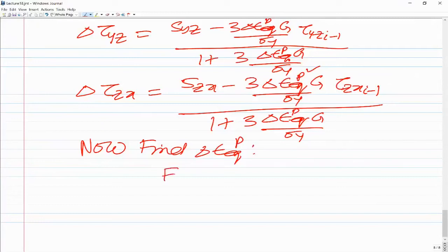So we say that f is a function of sigma and plastic work. Let me say for isotropic hardening, so sigma wp is equal to 0. I am now specializing to isotropic hardening.